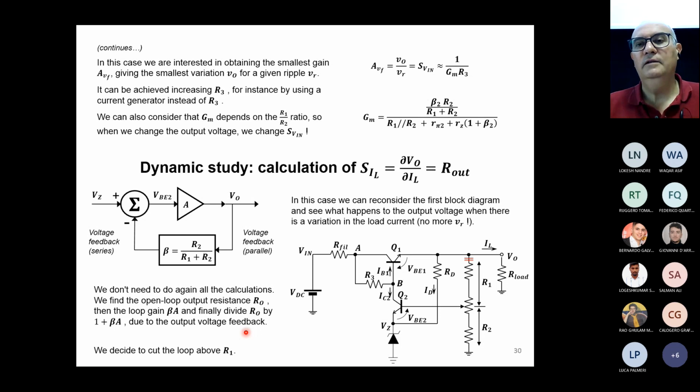If we want to calculate the resistance, before that we can calculate the open loop gain of the system itself. In this case, one should decide where to open the loop in order not to alter the gains. You remember, if you want to open the loop in some place, the total gain must not be altered.